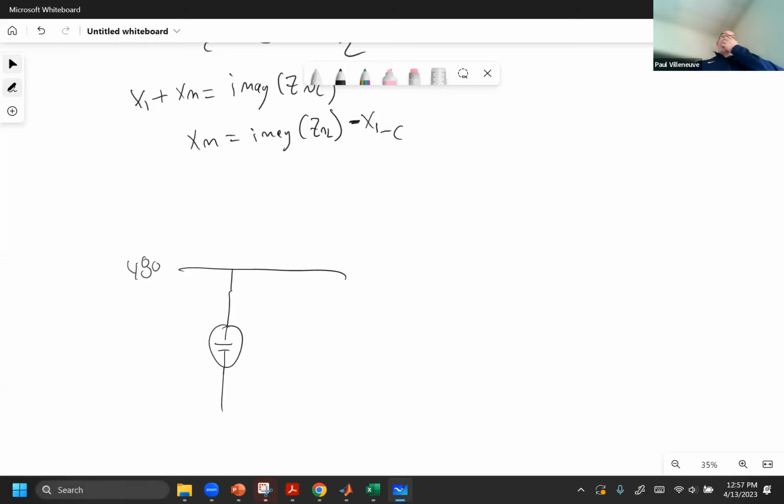Anybody know what a contactor is? It's not a breaker. It's a big relay. Big relay? Sort of, yeah. It's something that's designed to open and close many times. So it can operate 1 million times, 2 million times, and not get damaged, because it's designed mechanically to open and close. But it can't interrupt fault current. So you actually have a fuse, so that if the motor experiences a fault, the contactor will not try to open and interrupt the current, because it would actually get damaged.